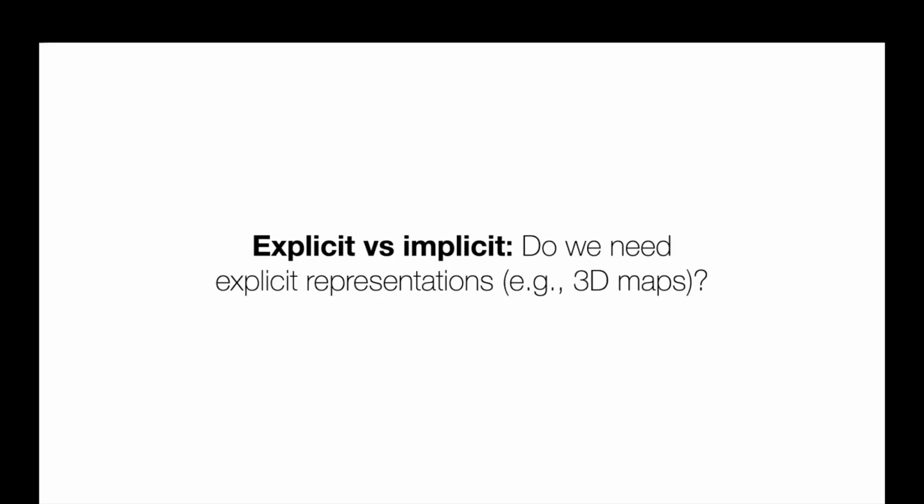Just a quick question for the panel. So scene understanding in this context also means making the scene relevant for motion planning. And one of the key components of motion planning is collision avoidance. And collision avoidance for robots doesn't really require 1080p images or something like that. What it requires is the relevant amount of data that is useful for the robot to just avoid local obstacles.